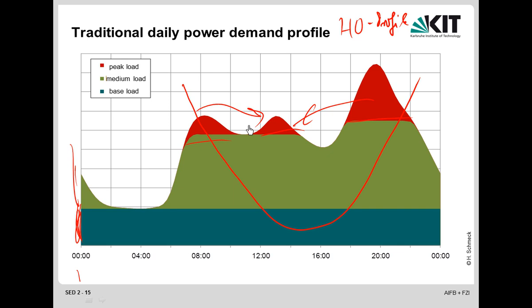Like in the moment where people get aware of those different power availabilities, and then they move their demand to times where there is more power available. And all these standard ways of estimating or forecasting the power demand, of planning the way power plants are operated, all this is no longer valid. Yeah, this is the traditional view, and it worked fine for a long time, but all of a sudden we don't have this base load anymore at all times, like last Sunday. Maybe it was because there was Mother's Day, and so nobody was cooking in the kitchen, and so there was even less demand at that time. Yeah? So a typical situation is that you have negative prices, something inconceivable for a traditional system.